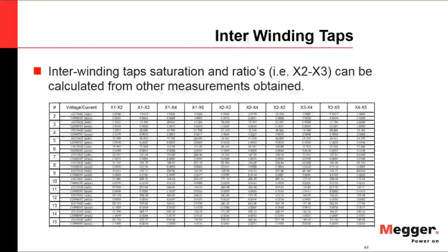You can clearly see here on this example that when we use the concurrent method, you can get the saturation voltage and current numbers in a tabulated way. And represented in this table, you will have every single subsection of your CT.